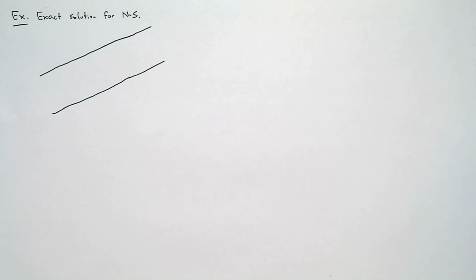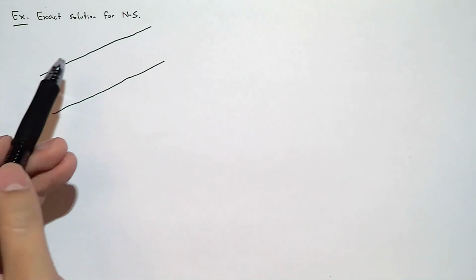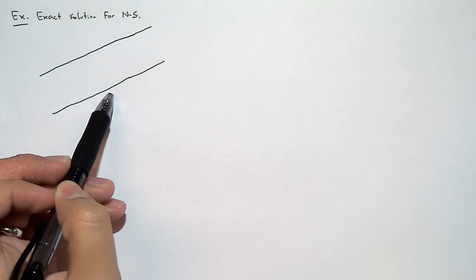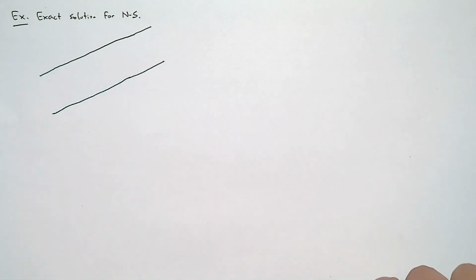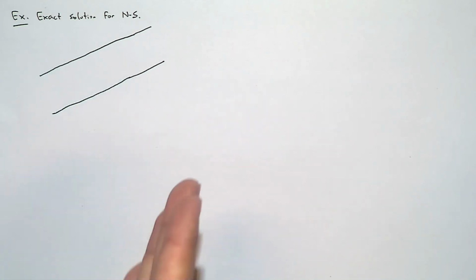Whereas for us in civil, we call a channel something that is bounded by three sides and open to the atmosphere on one side. I want to make that clear because I'm going to call this a channel, but it's not an open channel. It's not like a river or something. Fluid travels bounded on the top and the bottom, but not bounded on the sides. What that means is that we're looking at fluid traveling through two infinitely long plates.